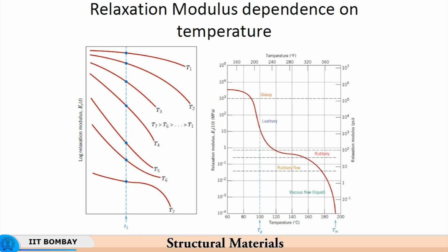In between, as the temperature goes down, you have partly the property of the solid mass of polymer and partly the viscous property of the liquid, so it's called a viscoelastic property. Both these properties come together, and that is the rubbery state that we see.